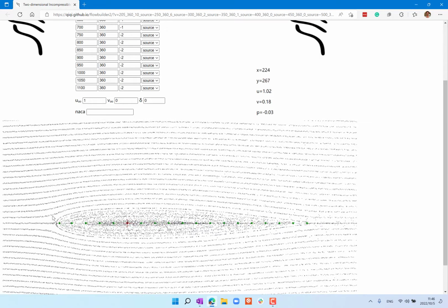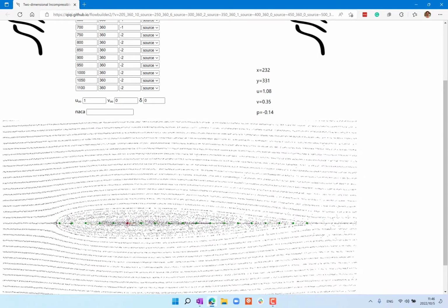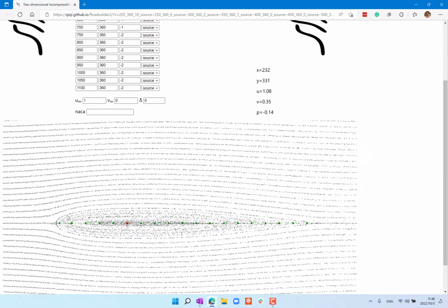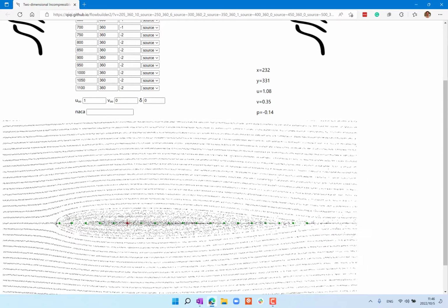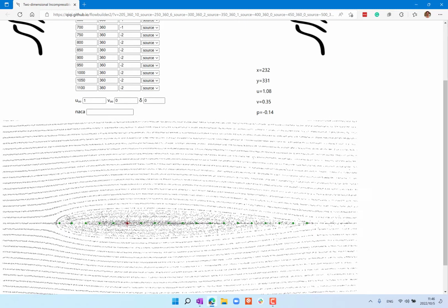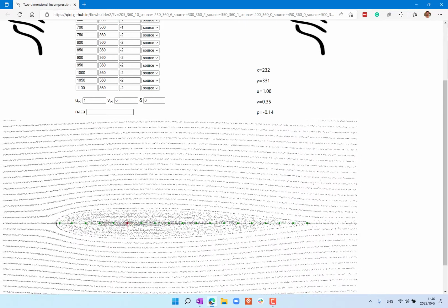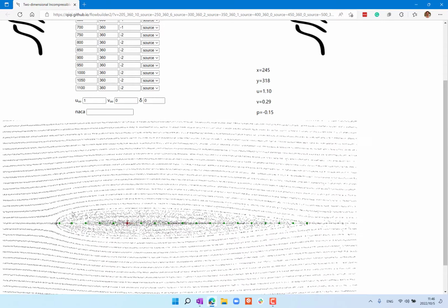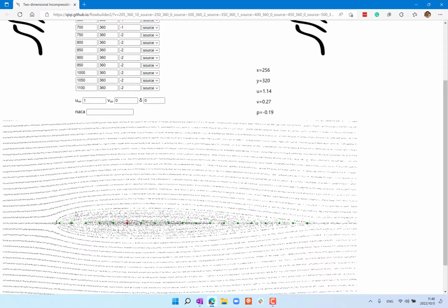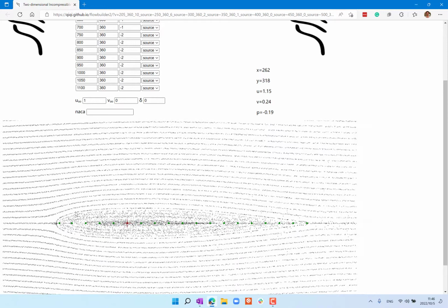That's starting to be a suction. And if you go downstream a little bit from this large source, you get even lower pressure, because now this source is not only contributing to the y velocity, but also pushing the flow along the x direction. So the fastest speed really comes from a little bit downstream of the high strength sources. Negative 0.19. That's where the flow accelerates the most.